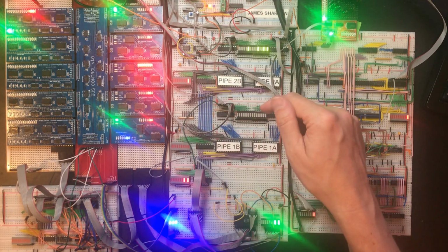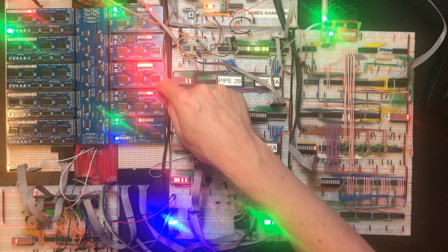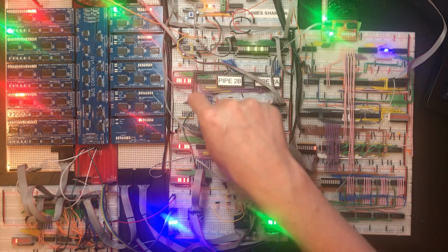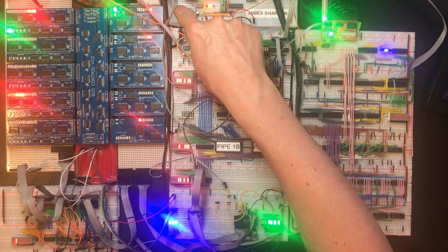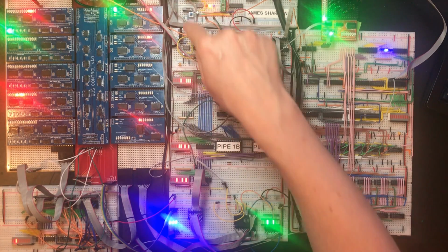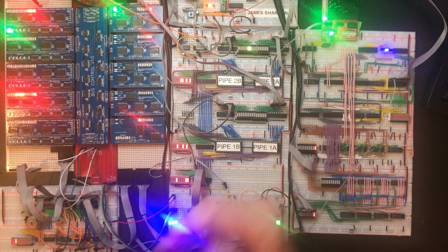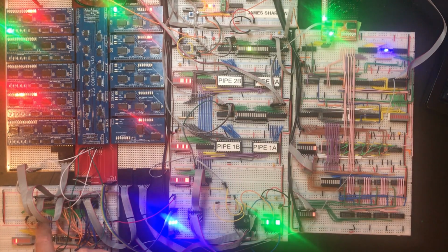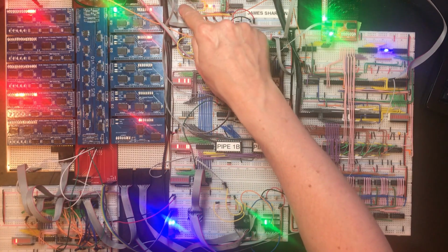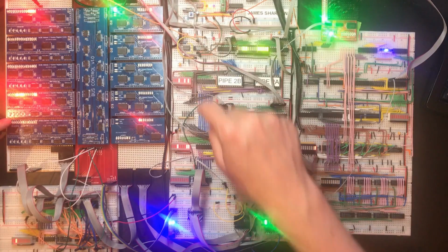Okay, so this is our load TL, 128. Good. Now we clear C and D. And then we've got move SI, TX. Yeah, so we've got gunk in the upper part still. Increment SI happens there. Now the important bit. We're going to load C from the address of TX. Now this isn't going to work. Should have chosen a register rather than TX, but we should see an assert, so this light should go out. Good. And now we're going to move D, SI, so we should see the assert to bus line.